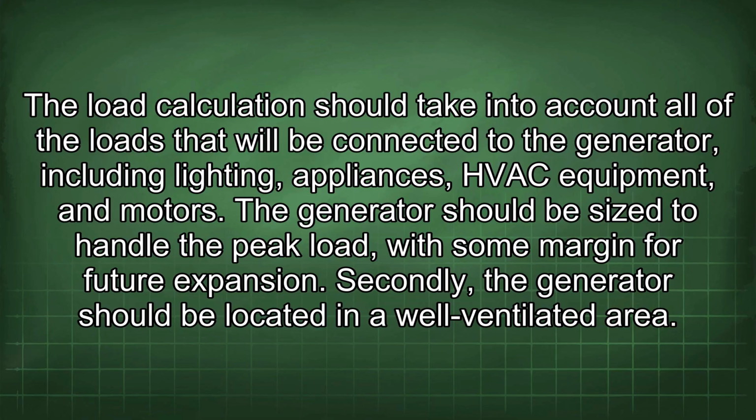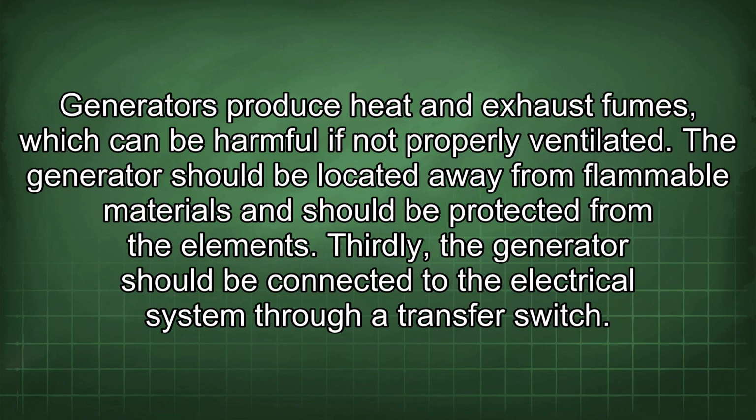Secondly, the generator should be located in a well-ventilated area. Generators produce heat and exhaust fumes, which can be harmful if not properly ventilated. The generator should be located away from flammable materials and should be protected from the elements.